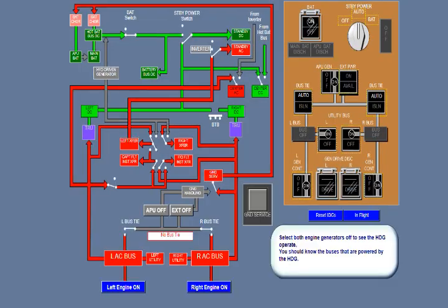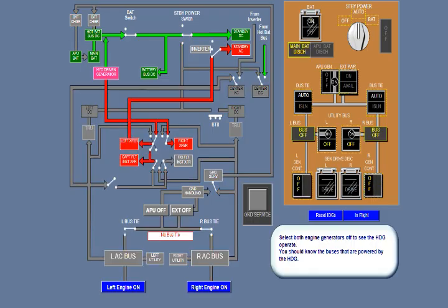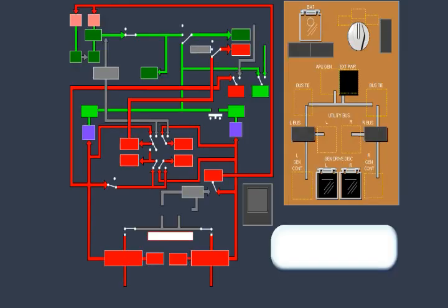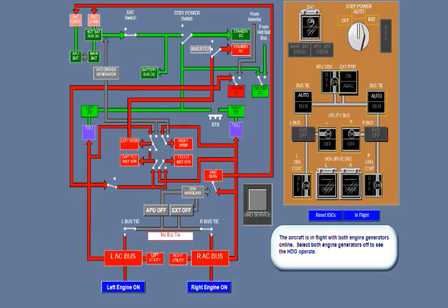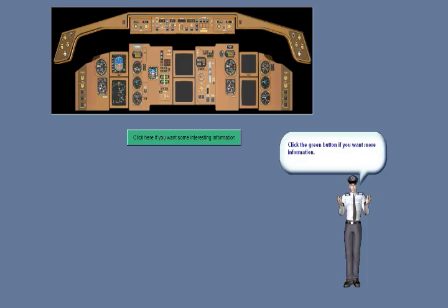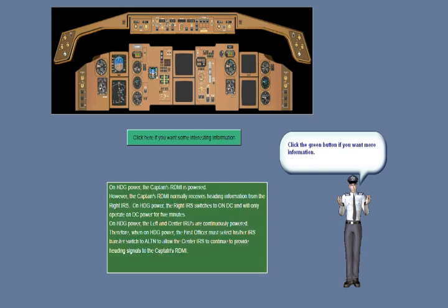The generator drive disconnect switch drive light and the generator control switch off light remain illuminated until the engine is started. The drive light extinguishes as the IDG oil pressure builds up, followed by the off light extinguishing as the engine reaches idle RPM. The engine-driven generator, in accordance with the AC bus power priority, automatically replaces external or APU electrical power connected to the associated AC bus.